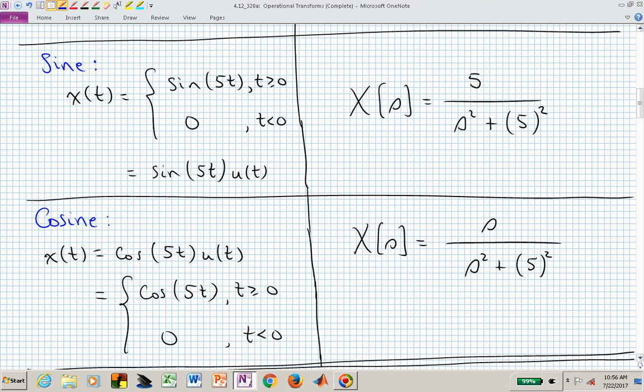In this case, we have then what's the second expression in our x of t is exactly identical to the first expression for x of t, and we then associate those two similar or equivalent expressions to the corresponding transform in the right-hand column. And here we have the frequency, omega, in the numerator, no s, so we have no finite zeros in our transform of the sine waveform. And we have poles at the values where the denominator vanishes. And in this case, we have s squared plus 5 squared.